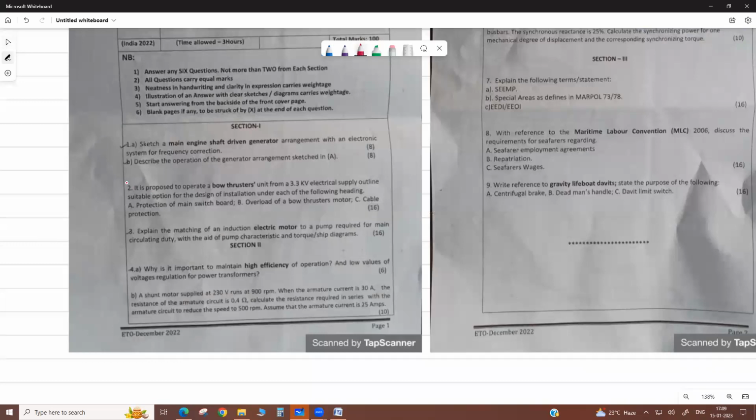You have to forget about this. This time at least it did not appear. Repeat. Okay, this is already repeated. This is okay, I have shared. Means you draw the pump characteristics and system curve. When the system curve and pump curve intersect, you can calculate the motor rating for a particular flow rate.